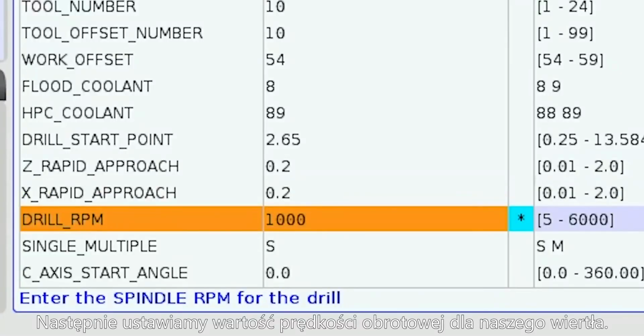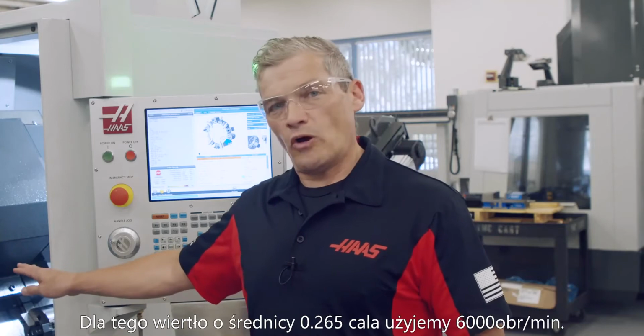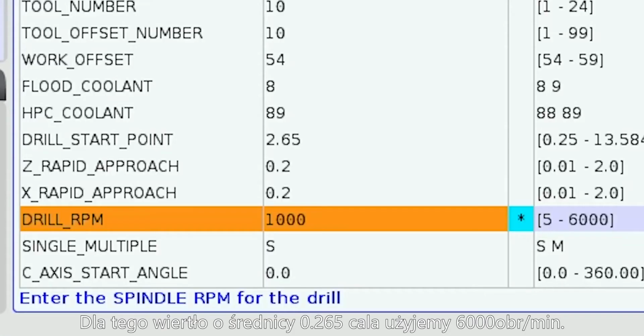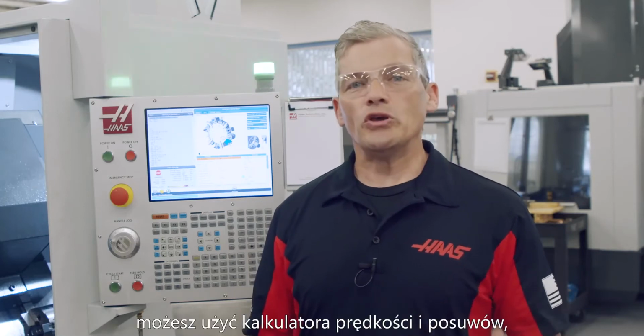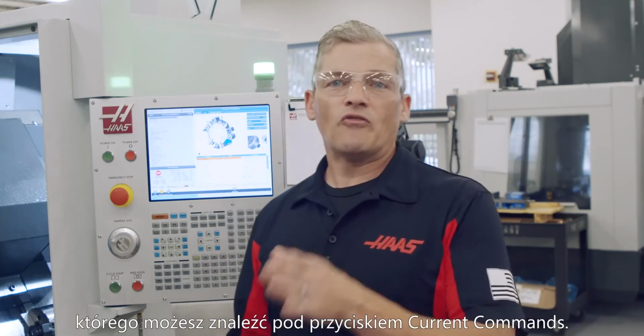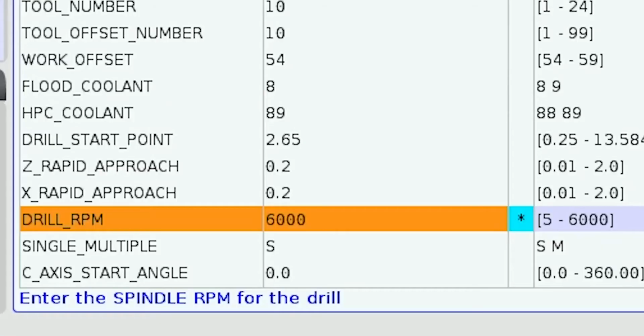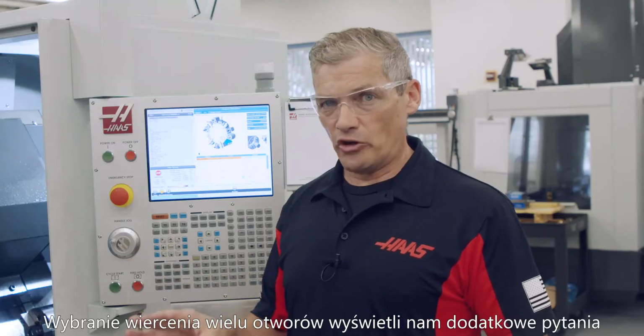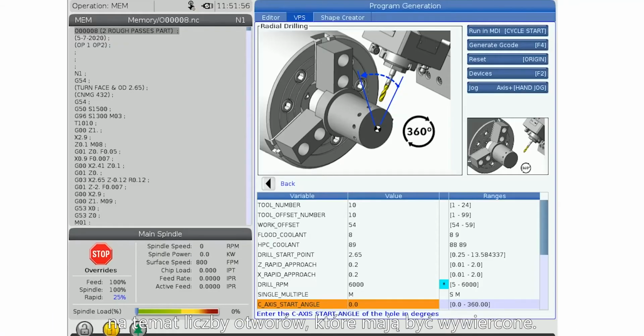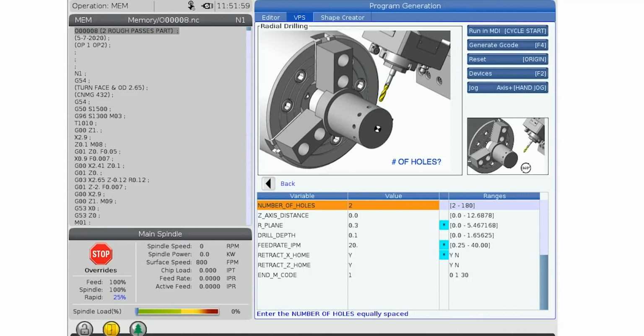Next, we set the RPM speed for the drill. For this .265 drill, we'll go with 6,000 RPM. If you need help finding recommended values, you can use the speeds and feeds calculator found under current commands. Next, we define whether we have a single or multiple drilled holes. I'll change it to M and press Enter. Selecting multiple holes will add a question for the amount of holes to be drilled.